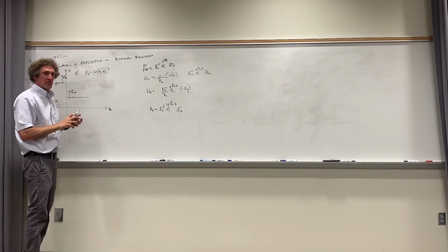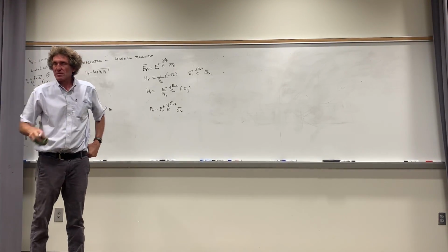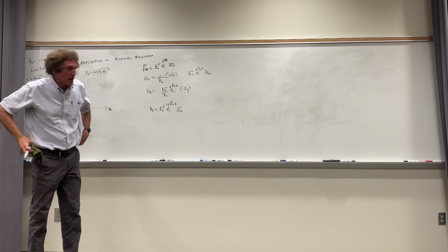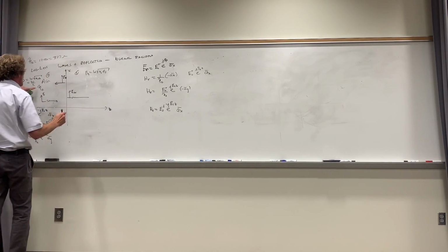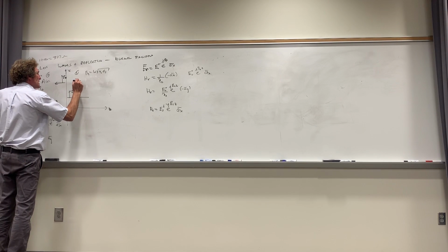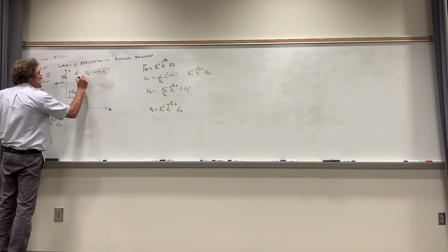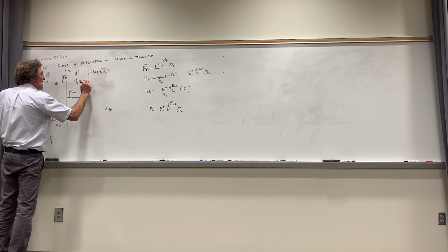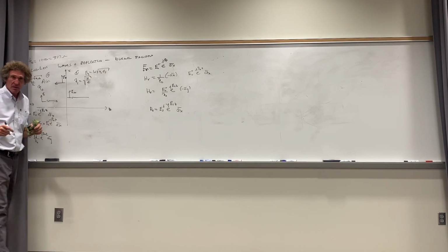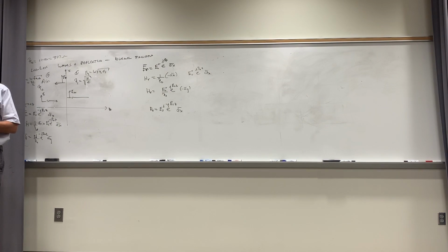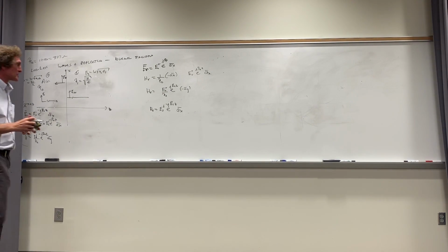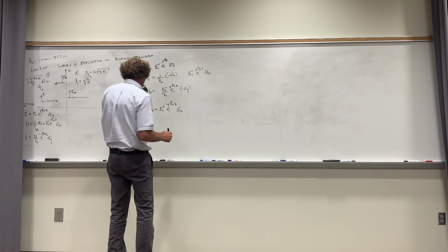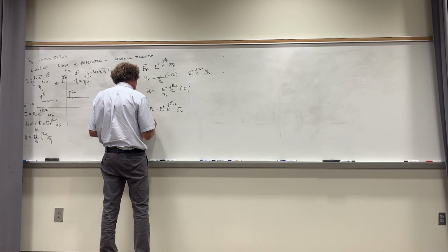The values will be different. When you do some of the problems, you appreciate this. And remember, this is eta naught, there would be an eta 1 here, and the eta 1, since it's lossless, would be the square root of mu over epsilon for that region. Not mu naught over epsilon naught. That's important to realize. So that's the transmitted electric field.